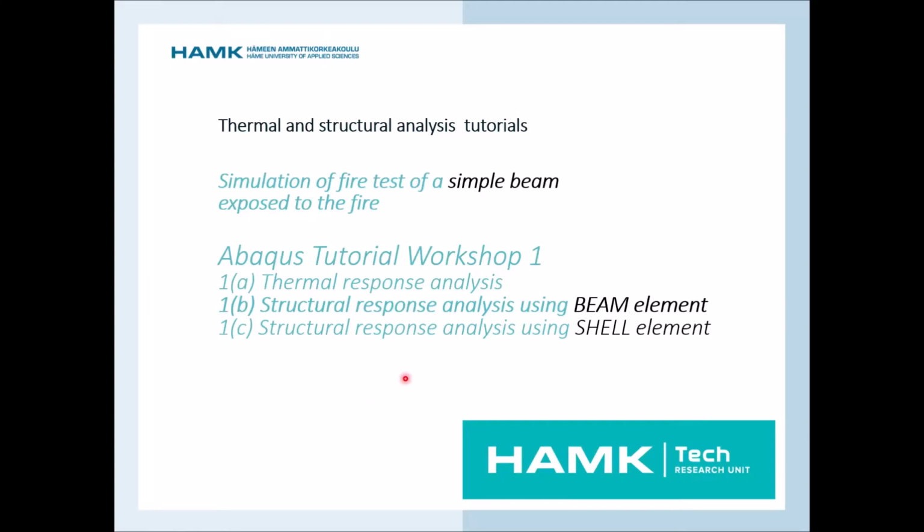Hello everybody, welcome to Abaqus Tutor Workshop 1. In this workshop we have three different analyses: thermal response analysis, structural response analysis using beam element, and structural response analysis using shell element. So in fire analysis, first we perform the thermal analysis to determine the temperature distribution in the cross sections. After that, we perform the structural analysis either using beam element or shell element and also solid element.